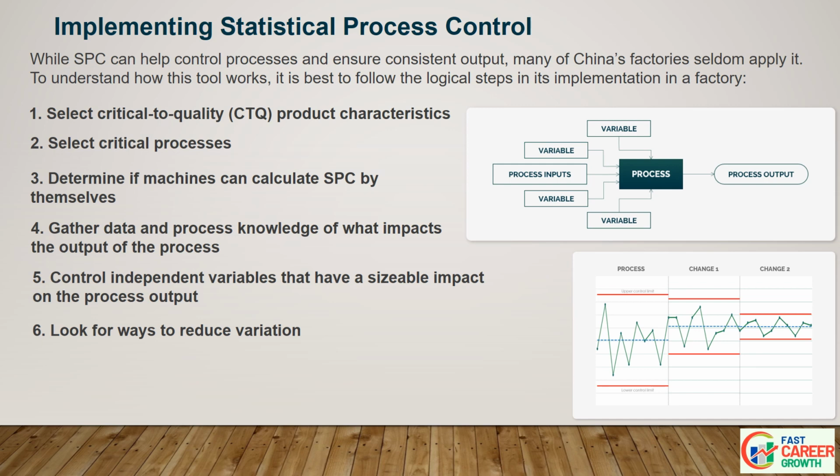Second, teach the production operators and leaders necessary calculations and how to plot them on a chart, such as a dot on the XBAR chart, the most popular tool. For simplicity, we tend to set a goal for the Process Capability Index, CPK, and let operators plot the evolution of that index over time.